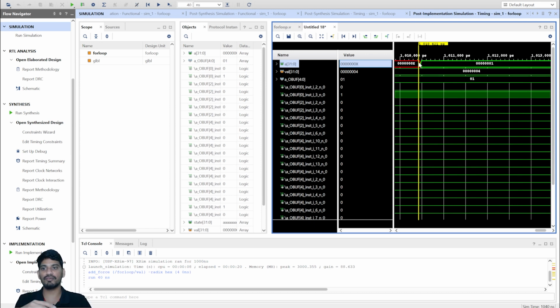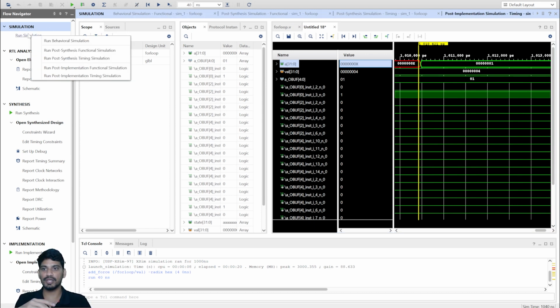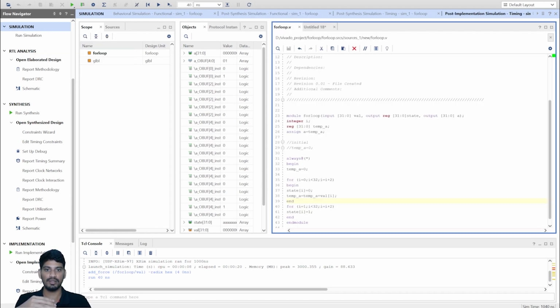This is the main difference between functional simulation and timing simulation. You should not believe the functional simulation; you should always believe the timing simulation, because that is the true output of your design. Okay. With this, I am concluding behavioral modeling as well. In the next session, we will see some advanced topics in Verilog, like what is switch level modeling and more.